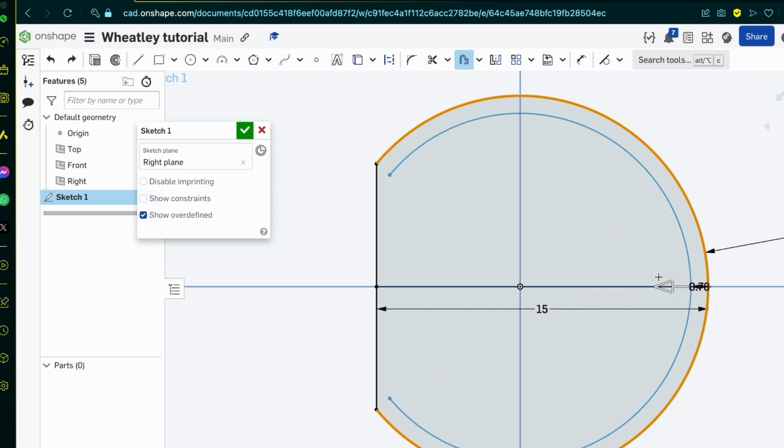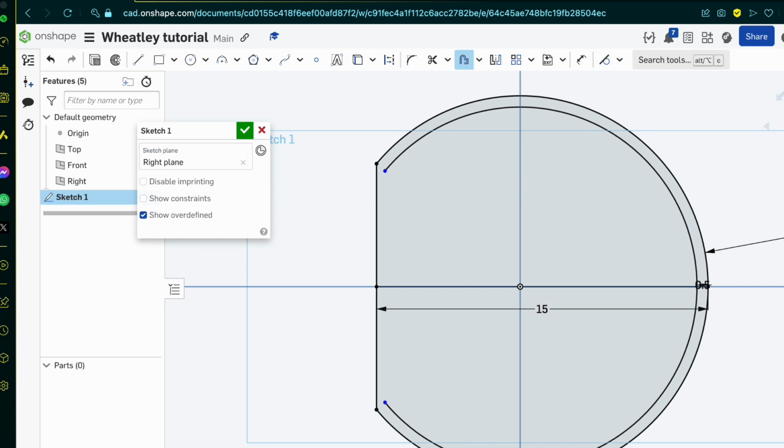So we want a wall thickness of 0.5. So enter, 0.5, enter again. Now take the circle tool. We probably should have done the offset before we trimmed the other circle so that we could get this, but never mind, this works too. So snap it there, press M again for trim. Now we take this bit off. This is going to bug me because it's now double lined.